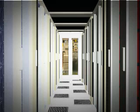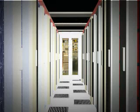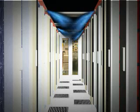Rittal's cold aisle containment system has been designed to be adaptable. The doors at the end of each aisle will fit 900, 1000 and 1200 mm deep enclosures. The roof panels also allow us to adjust the width of the aisle from 1.2 meters to 1.8 meters. The inclusion of a 100mm plenum, which increases the roof height, not only allows us to provide additional headroom, but provides important space for additional features, such as security webcams and fire extinguisher systems.